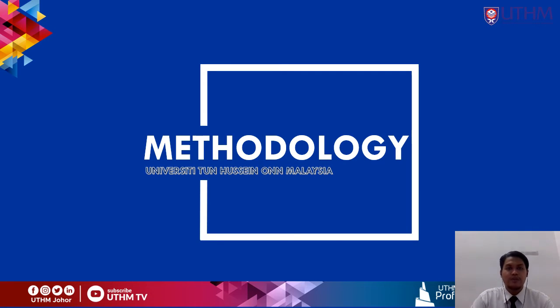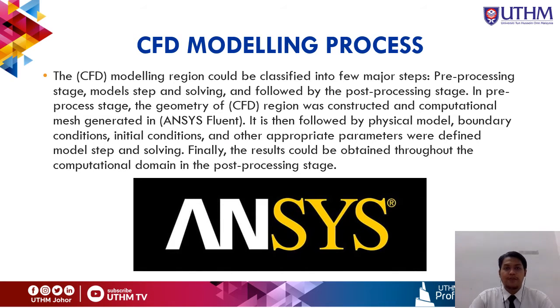Next, in chapter 3, which is methodology, I will explain about the CFD modeling process. The CFD modeling could be classified into a few major steps, which are pre-processing stage, model step and solving, followed by the post-processing stage. In pre-processing stage, the geometry of the CFD region was constructed and computational mesh generated in ANSYS Fluent. It is then followed by physical model, boundary condition, initial condition, and other appropriate parameters were defined, model step, and solving. Finally, the result could be obtained throughout the computational domain in the post-processing stage.